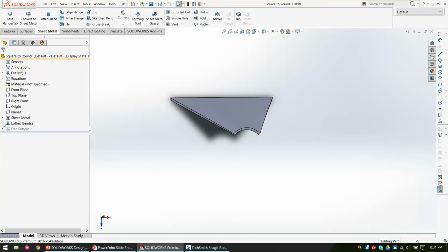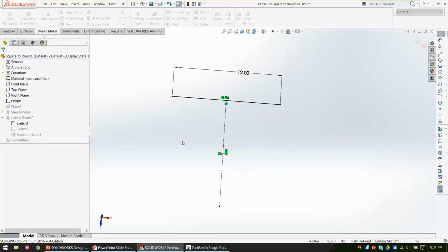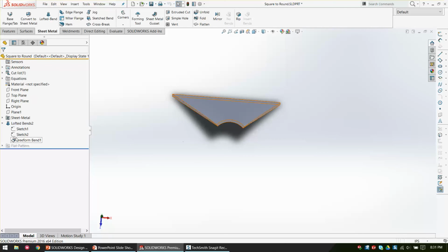So if I truly want to square it around, if it's all going to be in line, I only need a single dimension for my square. It's 12 inches square, center origin, draw two lines to make them equal. I watched somebody do a squared around once and they added 2 dimensions here. I'm like, why? If you want a 14-inch tomorrow, you have to change 2 dimensions and you have to do math. Don't do math.